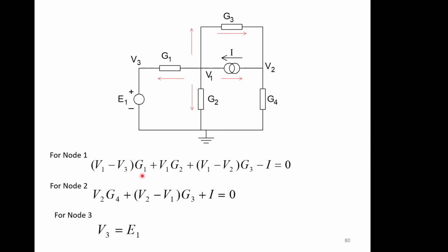So again, we apply a node equation. Now node V1 is a little bit more complicated, it's got 4 currents leaving it now. They all add to 0. We've defined them leaving, so we should be getting the idea now. So we turn the resistances into conductances just for the ease of writing it, otherwise we'd have to have 2 lines of text.